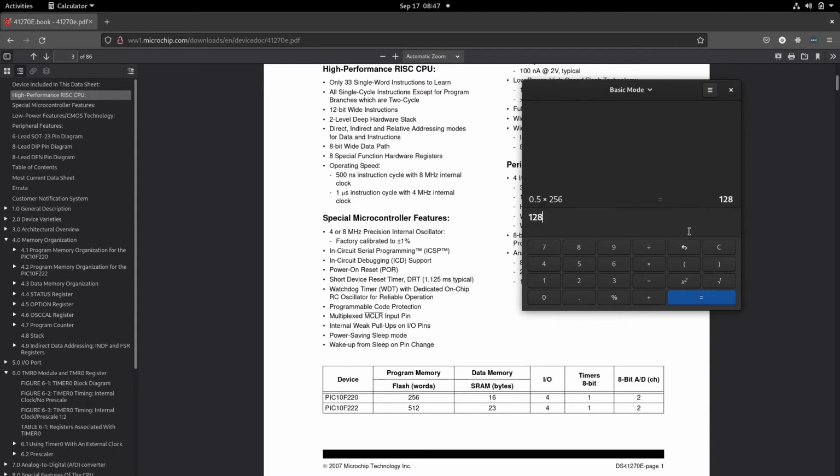So we will read the same value at TMR0 register every 128 microseconds. If we divide 1 million microseconds, which is 1 second, by that, to calculate the frequency, we will find about 7,800, like 7.8 kilohertz really, of a signal that we can generate with our timer in its fastest mode. So we don't need to go as fast, because when you're driving an LED, there's this thing called persistence of vision.